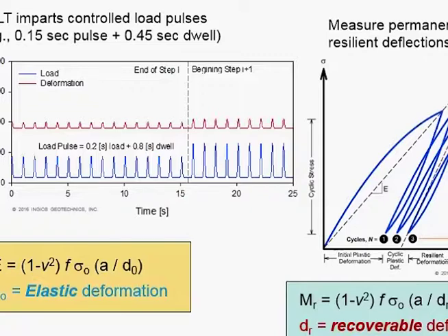Interesting, the gentleman from Illinois showed the picture from the Illinois AASHO road test. When you go back and look at the geotechnical data, they used cyclic plate load test results to calculate modulus. They only did 6 cycles though, and it was probably a lot of work back in the 50s when that was done. So we're really not inventing this thing, we're just going back and getting the data. But now we can do hundreds and thousands of cycles to capture that response.